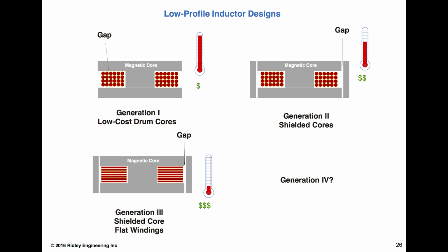There's a request for clarification here. In the presentation, it was mentioned that the discontinuous conduction mode is advantageous because it enables ZVS. Isn't it ZCS since the inductor current goes to zero? Yeah, there's a lot of notation on what ZVS and ZCS means. Actually, on one of the transitions, it's both. You're turning on with zero current.